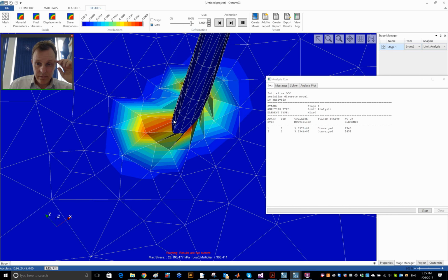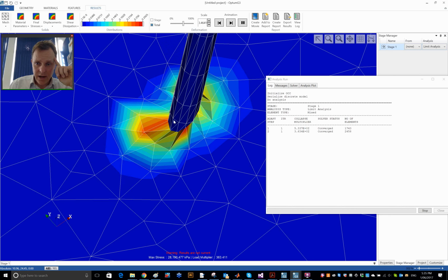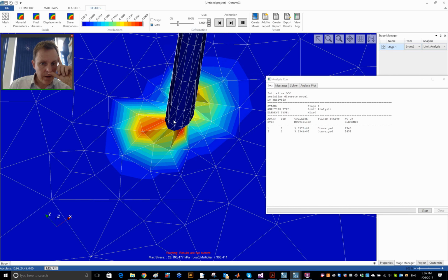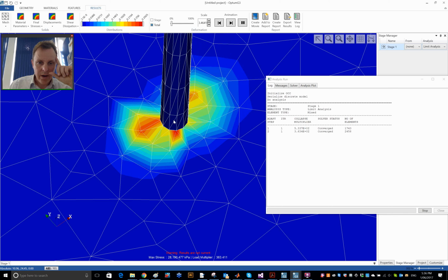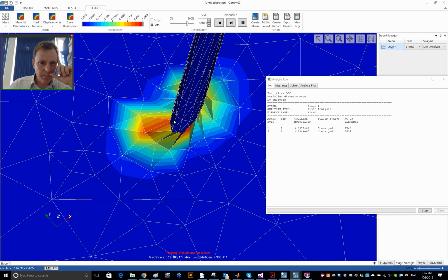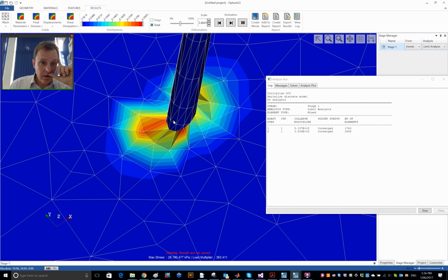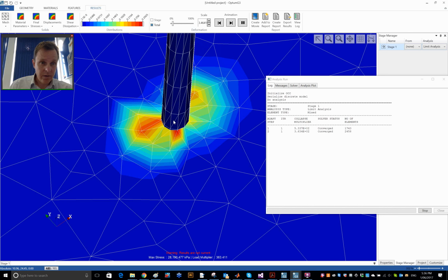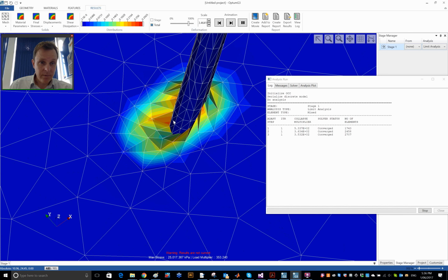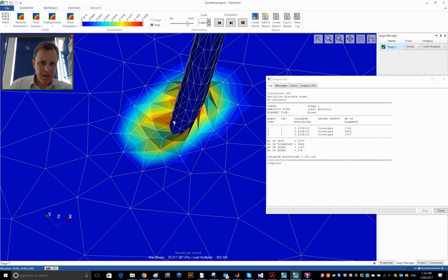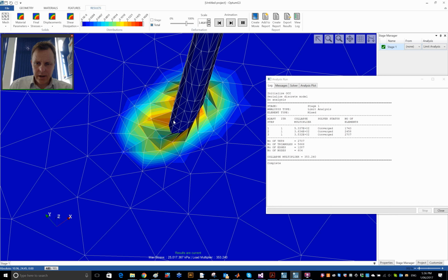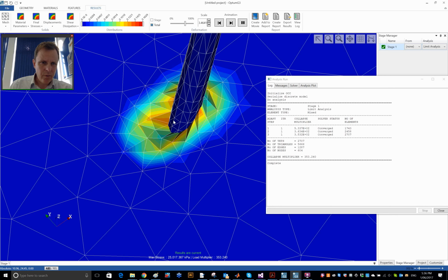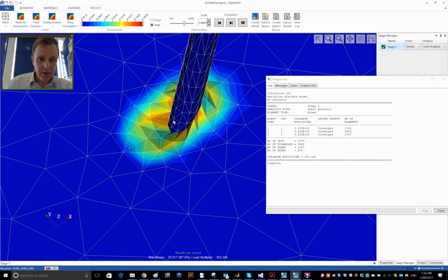And as I've said before, these analyses do take quite a bit of time. There's just no way around that. 3D analysis is just a lot more time consuming than 2D analysis. So our strategy here with G3 has been twofold. First of all, use very accurate finite elements. We've developed some new elements, among them this mixed element, and secondly, use mesh adaptivity. And in that way you can actually, in far most cases, get away with a very moderate number of elements.